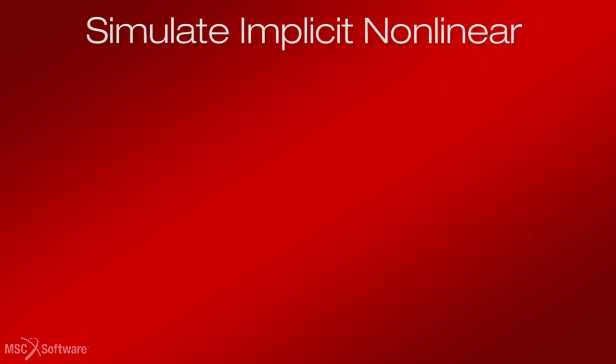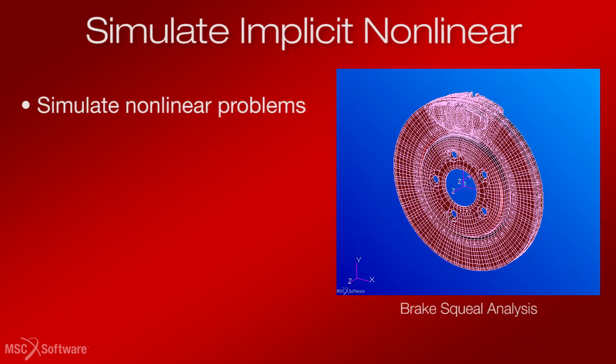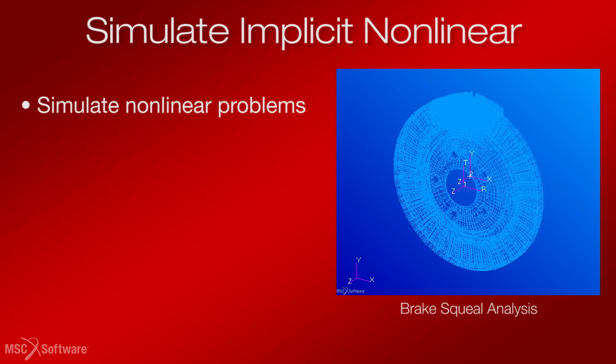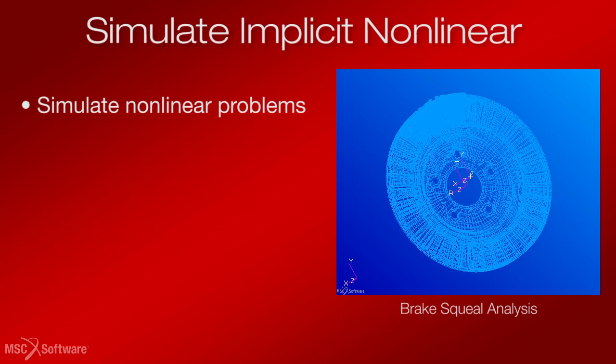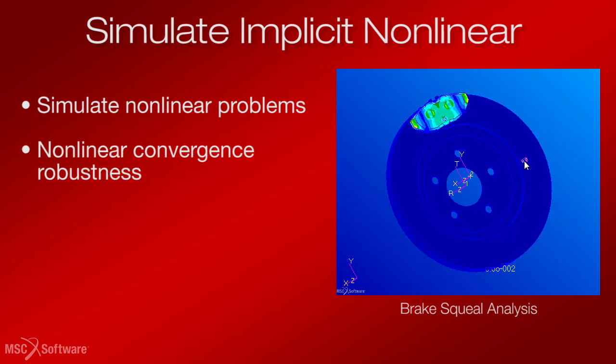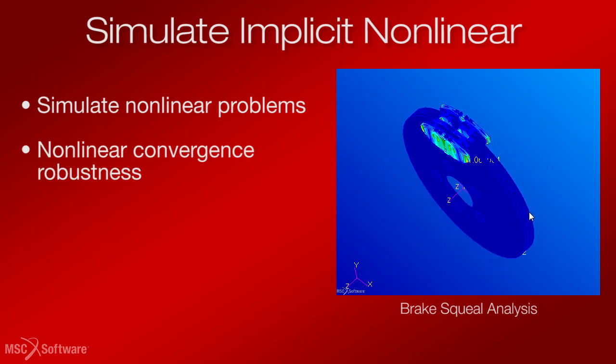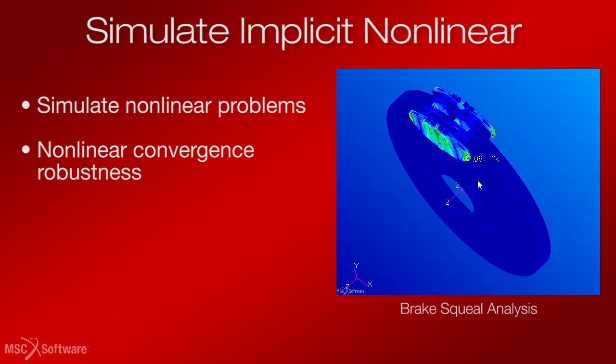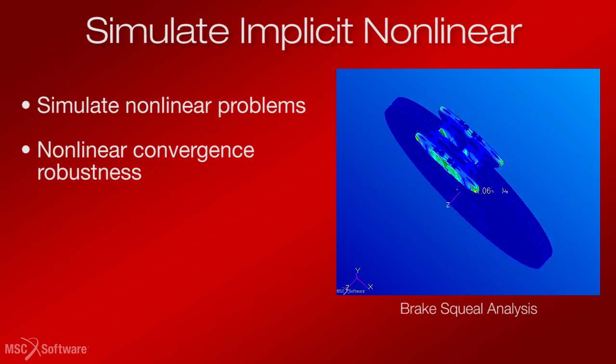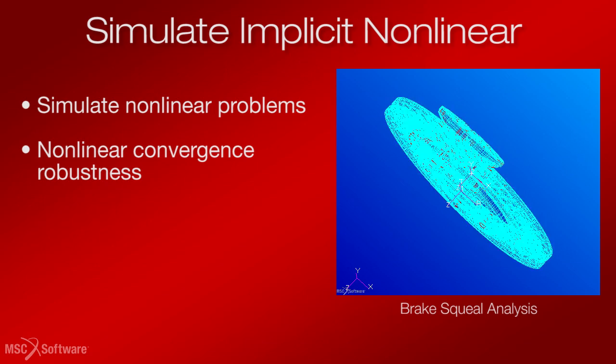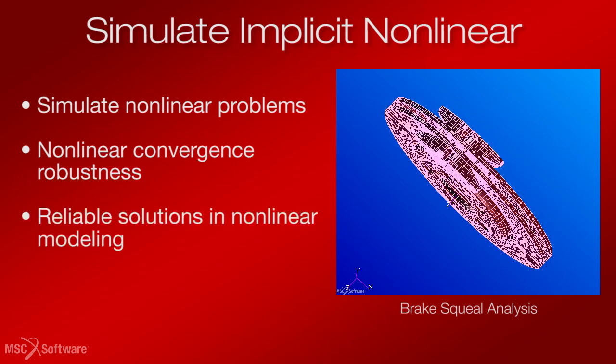Through an optional module, users can simulate nonlinear problems including geometric, material, and contact nonlinearities. In this release, nonlinear convergence robustness has been enhanced with a new adaptive stepping procedure and a number of predefined settings that are tuned for mildly nonlinear to fully nonlinear models that make it easier for linear analysts to get reliable solutions in nonlinear modeling.